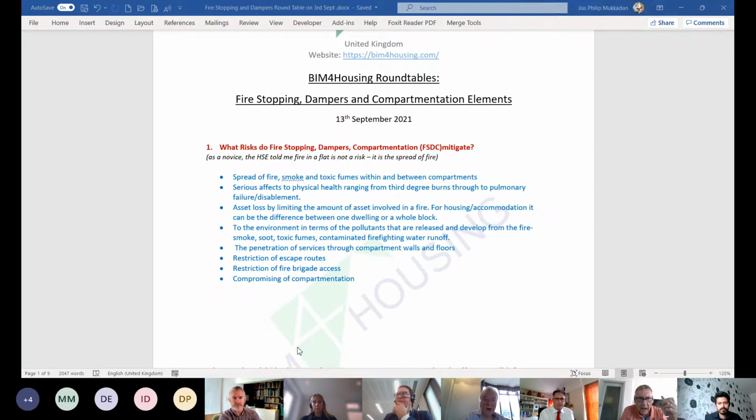Yeah, the points that I made are because the title indicated flats and apartments. Houses are slightly different. Generally you don't have compartmentation inside the flat or the apartment. You used to have fire doors inside, but generally speaking you don't now, because people just propped them open anyway. The point is to remain in place as a concept: the flat or the apartment would be its own compartment. So the flat where the fire is, it stays in there and it can't get into any other flats.